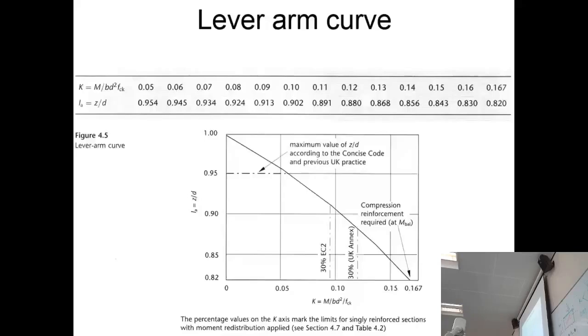However, with this chart, you've got to make sure that there aren't some conditions on it. This chart is based upon there being moment redistribution. We do not use this chart. So if you get the book Moseley, reinforced concrete, which is the book that I used, you'll find that there's this chart. Don't use this. It's about beams with moment redistribution. We'll do that in structural analysis.